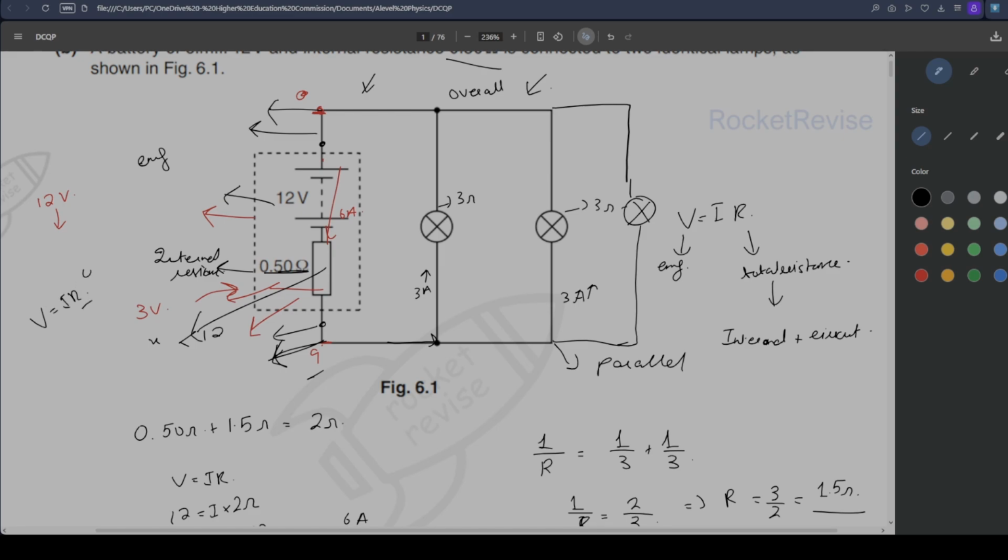This R is going to be constant. But if we have a greater current flowing through the battery, then this resistor is going to take up more of the voltage of the EMF, it will consume more. That's why we need to see that if our circuit's resistance decreases, then current will increase, and that's going to result in a lower terminal voltage. If our resistance increases, then current is going to decrease, that means we get more voltage at our terminals.